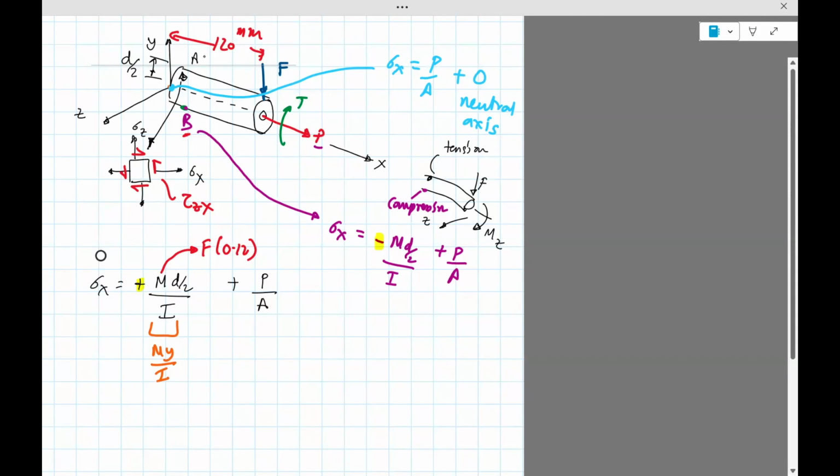At 3 o'clock, yeah, then you'll have to just sub in the right y, right? You'll have to see if it's above, which will be positive stress, or below, negative stress, and then you just substitute the right y. So at 3 o'clock, you need to find the y by computing the height at that point. No, it won't be. y is the distance from, so you're saying this point. No, 3 o'clock is zero. At 2 o'clock, the height is whatever that is. Yeah, cosine or sine, depending on how you choose the angle.